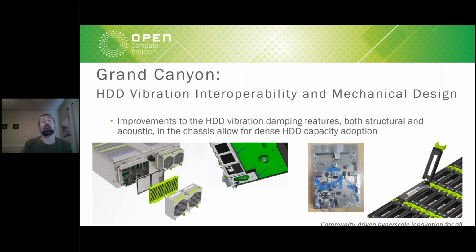The design accommodates options to mount fan louvers to reduce air leakage during a fan failure, and you can see them. I don't know if you can see my mouse, but this green square here is the elastomer padding, and that's the fan louvers. The idea there is that the louvers close when the fan fails, preventing air from leaking back out, and that allows the remaining fans to run at lower speeds compared to if there were no louvers installed.